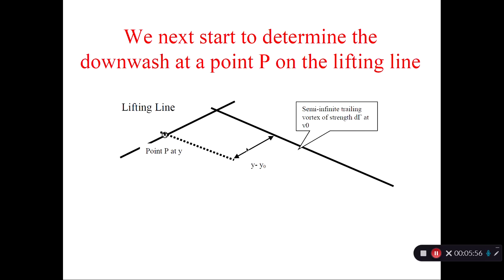If you take one particular vortex, it's either bringing circulation towards the wing, so think of it as a screwdriver advancing in this direction, or it's taking away circulation, that means a screwdriver spinning in the opposite direction. Either way, it's got some strength called delta gamma, which is a change in the gamma between one part of the wing and the other part of the wing.